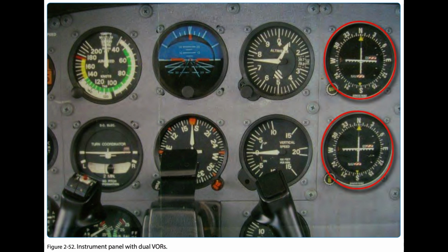2. Active flight plan check. The active flight plan should be checked by comparing the aeronautical charts, departure and arrival procedures, and other applicable documents with the map display.